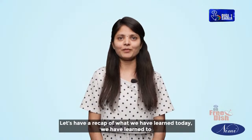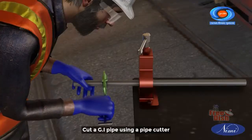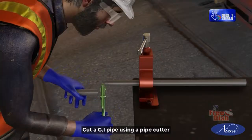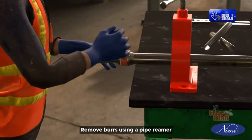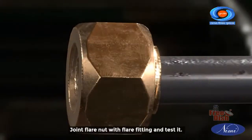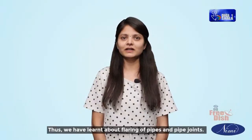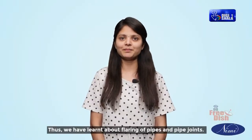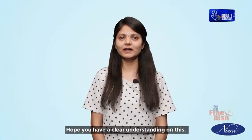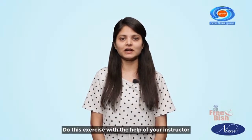Let's have a recap of what we have learned today. We have learned to cut a GI pipe using a pipe cutter, remove burrs using a pipe reamer, flare the pipe end, join the flare nut with a flare fitting and test it. Thus, we have learnt about flaring of pipes and pipe joints. Hope you have a clear understanding of this. Do this exercise with the help of your instructor.